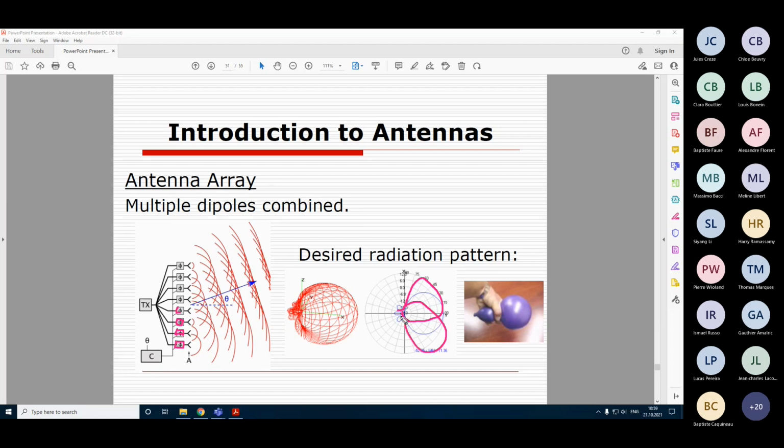So we can avoid the need to climb this tower and tilt this antenna mechanically. We can instead change some currents, and this antenna will act as if it has been rotated physically. So by using this approach, we can form this radiation pattern on the go by changing these signals. This is also a very nice thing.